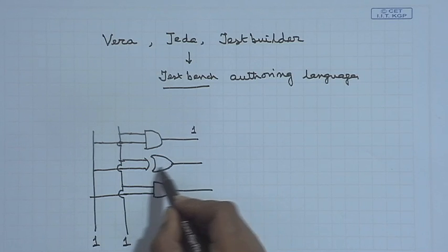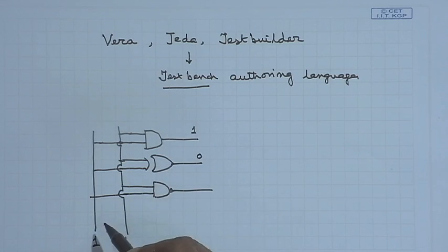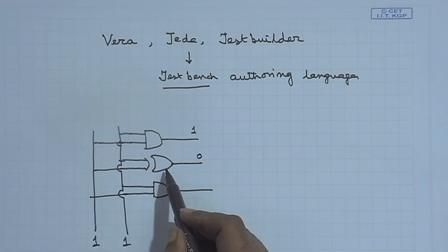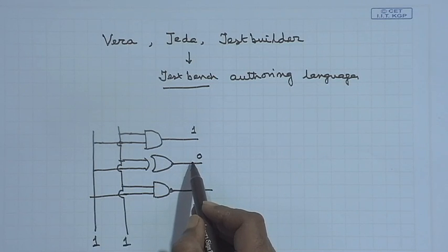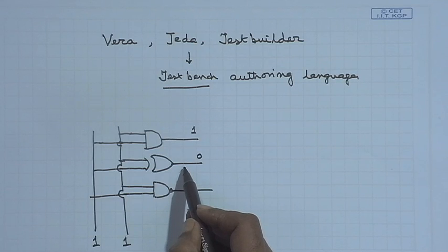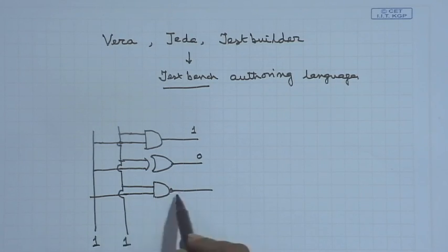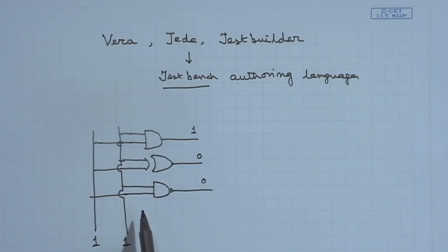But if I look at this, 1 1 is giving a 0 here, but that does not tell me whether this is all right or not, because a 0 0 would have also given a 0 here. It may be stuck at 0 also. I do not know about that. 1 1 will also give a 0 here. So, I could not excite this as well.